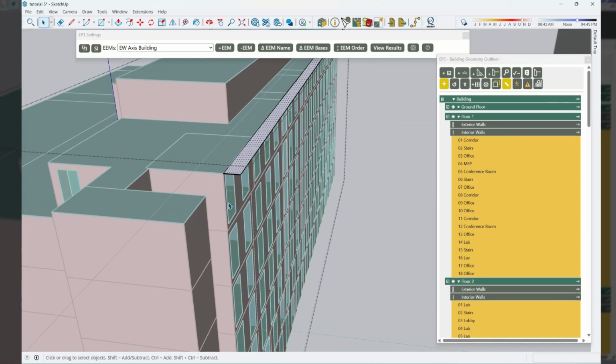And then I'm actually going to angle this. So I'm going to hit Q, which gives me the protractor or the rotation tool. Once I had it in, so when you hit Q, it will snap to any axis. So I want to snap it to the red axis. So when it does, I'm going to hold Shift down, and then I can grab a first point. I don't have to grab Shift anymore. And then I can grab another endpoint and I can rotate it. And if you look in the lower right, it's giving me an angle. So we can do an angle of, say, 30 degrees.